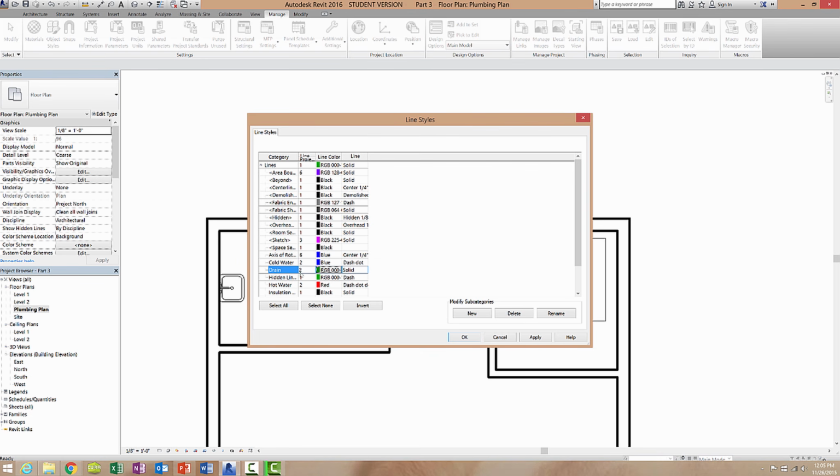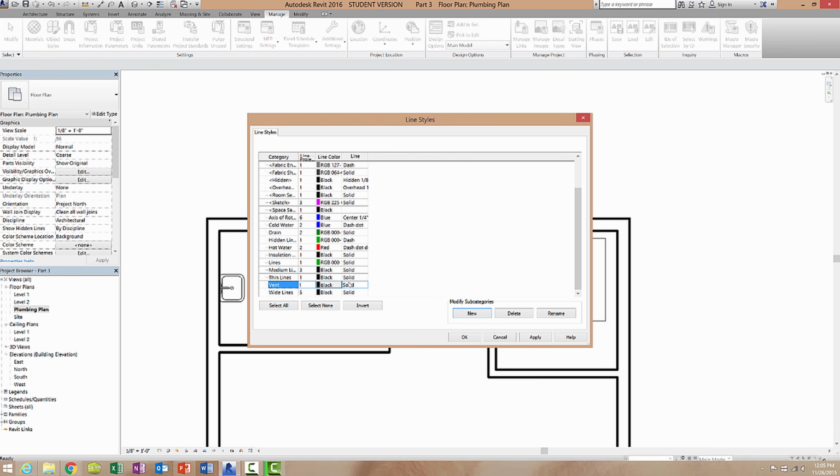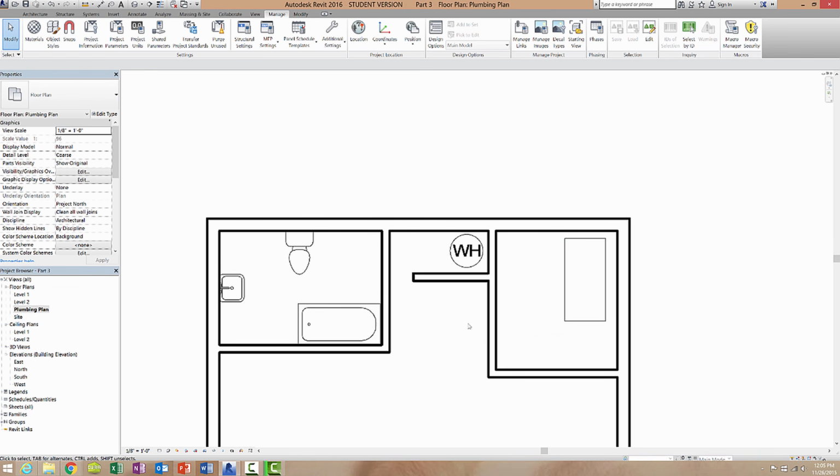And we also have a vent, which is to help those foul-smelling odors from exiting into your house and causing issues. So if we wanted to, we could create a vent, and it is 2 thickness. It is a black line, and it is just a consistent dashed black line. So I'm going to go to dash and click on that. Hit apply, hit OK, and we've created all our line types.